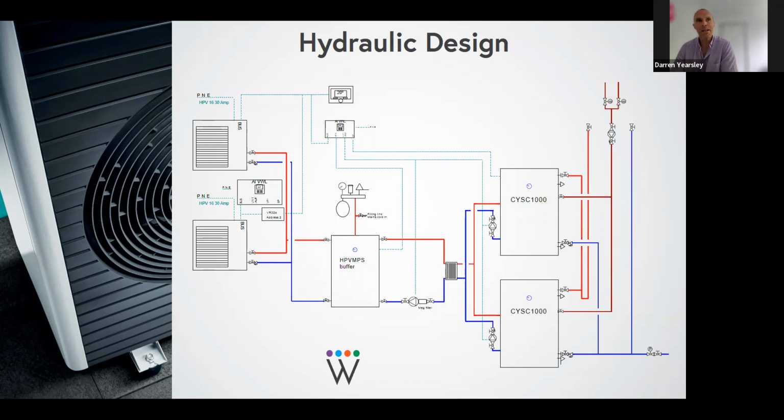So when the solar system is in production, rather than have that backfeed the building and be used to run lights and fridges and everything else on standby, we can preferentially use that energy and run it through the heat pump, because every kilowatt of electricity you run through the heat pump, you yield 3 kilowatts of hot water. So that is your preference.